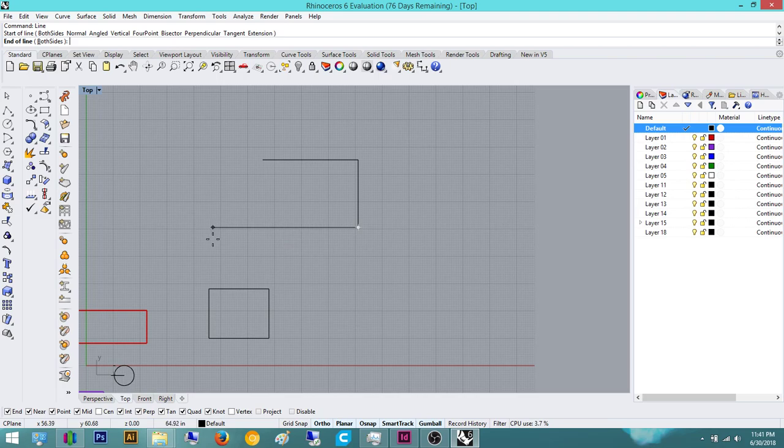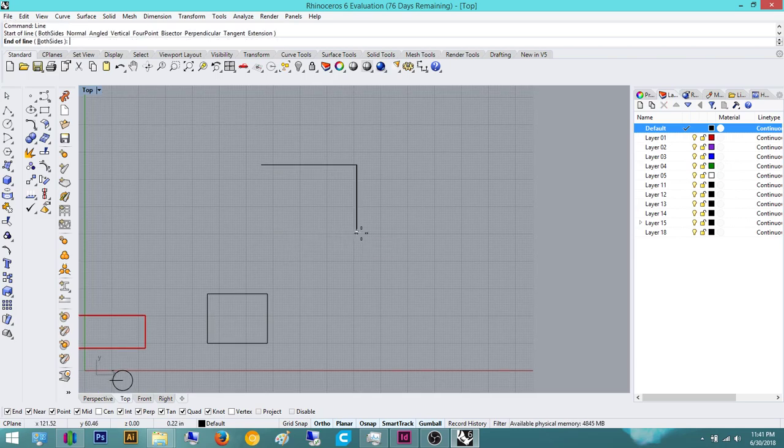One thing I forgot to say. When you're drawing something flat, instead of doing the triangle method I just showed, you can do line. And I know I want this to be ortho. As you can see, it says 37.6 and then 0 degrees on ortho, which means it is perpendicular to this, and orthographic, right?